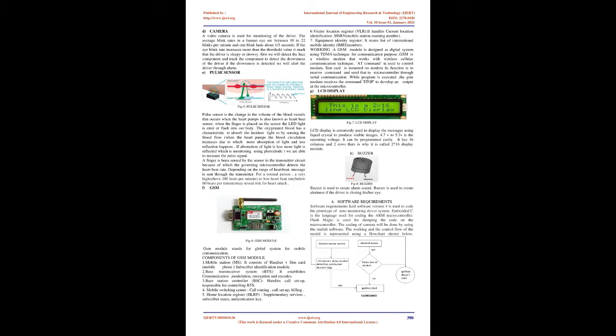Erasing of data in the full chip takes 400 milliseconds. 256 bytes of programming is done in 1 millisecond. Power conserving modes are idle and power down.